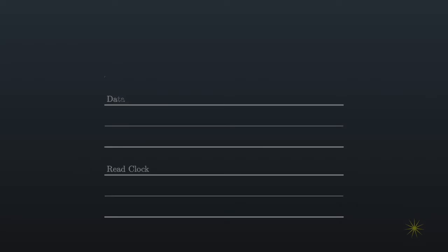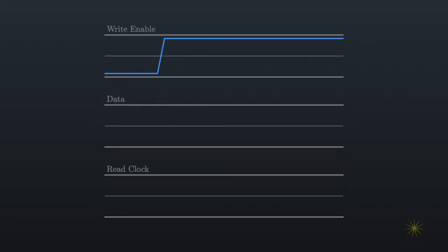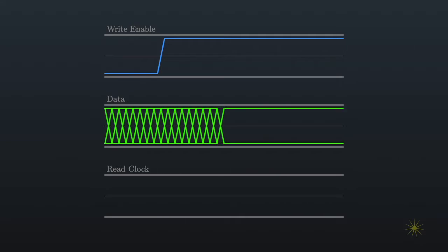What this implies is that when we turn on the write signal to our tri-state gate to write the results to our bus, or when we select a desired component in our arithmetic logic unit, there will be a short delay before our results show up. This delay is called the propagation delay. It is associated with how long it takes for our answer to propagate to the output.